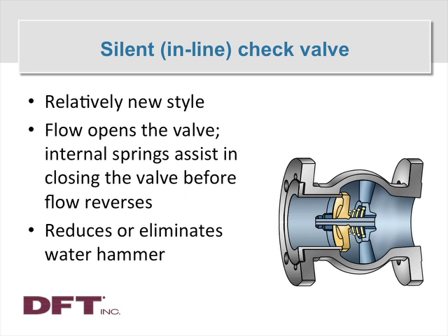The style of the valve, because the flow is staying along the axis of the pipeline, tends to reduce turbulence. Typically, these are very robust and reliable designs, and there's a broad range of applications possible with these products, from cryogenics, which would be minus 320 F or minus 196 Celsius, or extreme elevated temperatures, again with the appropriate materials, 1200 F, 650 Celsius would be possible.